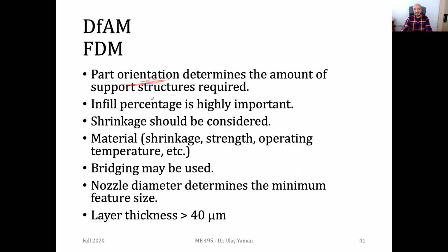design. And why don't we actually want to have support structure? Since it's waste of material, and it, again, decreases the surface quality, it increases your manufacturing time and post-processing time. So that's why we're always trying to have some designs where you have no support structure or less support structure. And you can do it by modifying your design or orienting your design on the table.